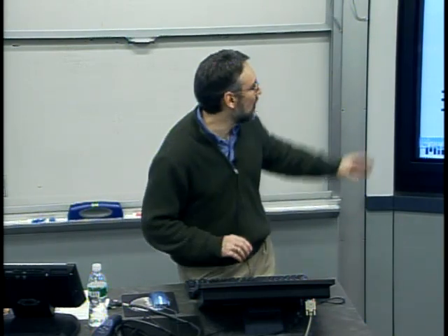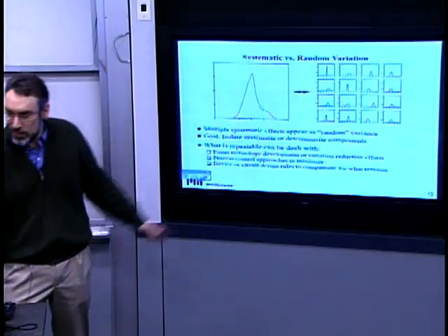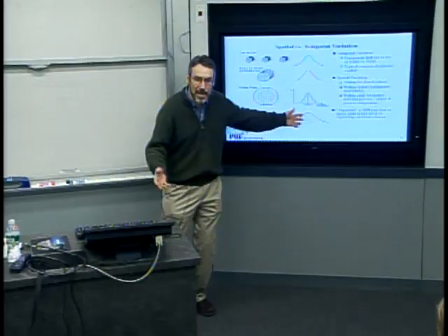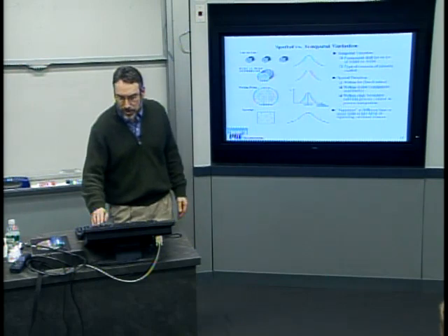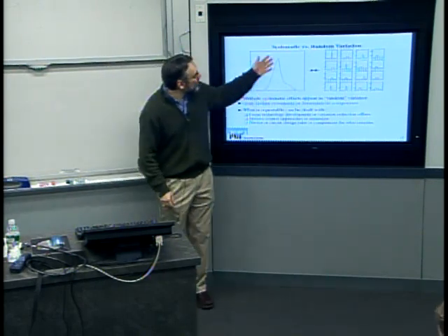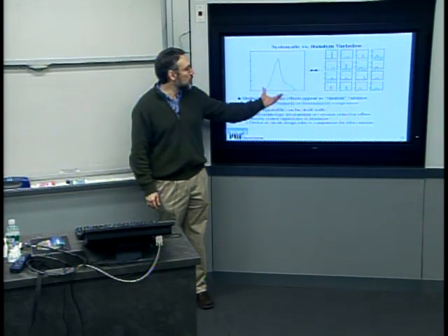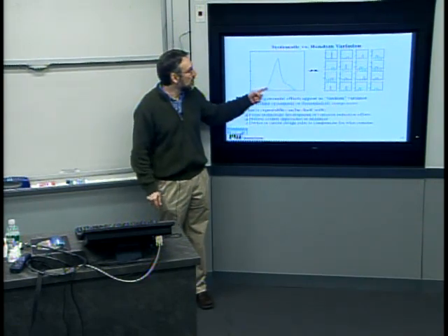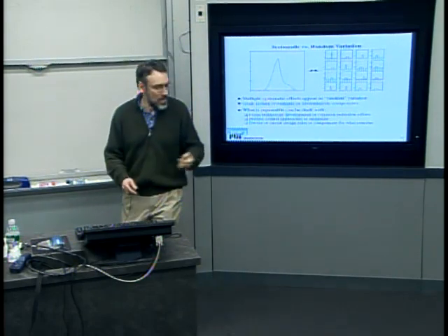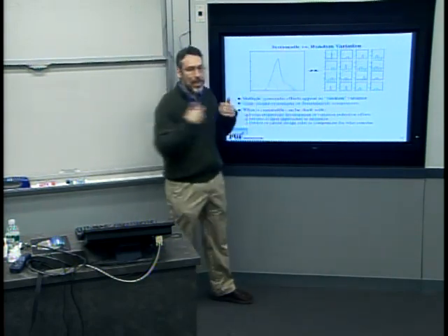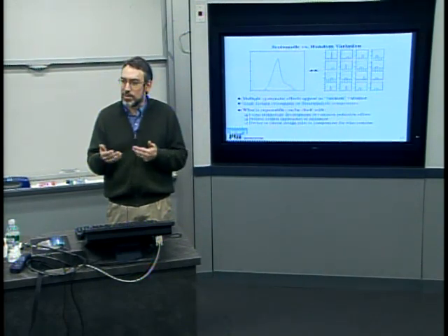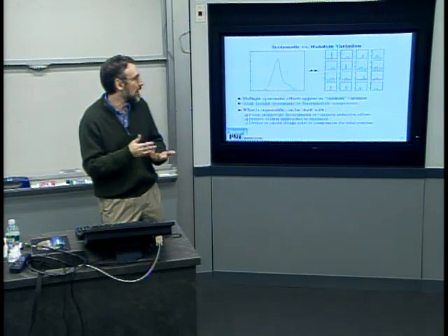Now, if we were to actually zoom in on one of those distributions, what's also going to be very interesting is trying to understand what the sources of variation are at each of the spatial scales. And you might have a fairly complex distribution, say, over channel length. And what's often very much the case and very interesting is that total distribution is the compounded effect of multiple additional sources that are sort of convolved together.